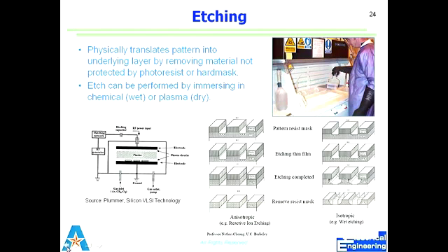So that's the difference between isotropic and anisotropic etch for dry etch. Wet etch has to do with the crystalline planes. This is dry etch. We'll look at the anisotropy of wet etch. Any questions?